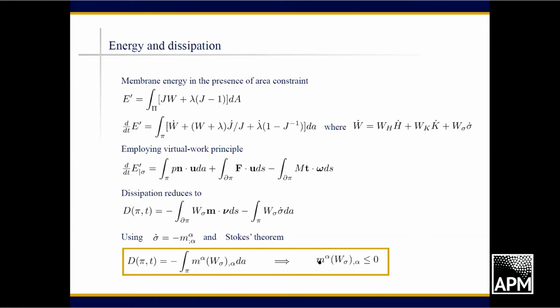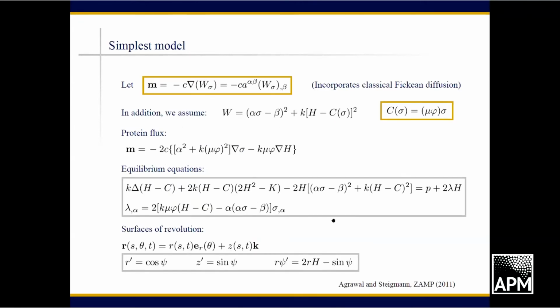And so we have effectively a constitutive inequality analogous to what one finds in heat transfer, which is that the diffusive flux is opposed to the gradient of the chemical potential in the surface. And so we would adopt a simple constitutive equation that is such as to satisfy this identically. For example, in the classical situation, the diffusive flux is a negative constant, that is to say, C is a positive number, the diffusivity, multiplying the gradient of the chemical potential in the surface.